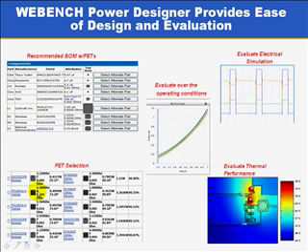It shows you the FET selections it has done for always the low side and the high side FETs over here. You can choose which pair is best for you. And then you can go and do electrical simulation, like the switching curves here, and you can even go and do thermal simulation. That shows you where the hot spots on your board will be.